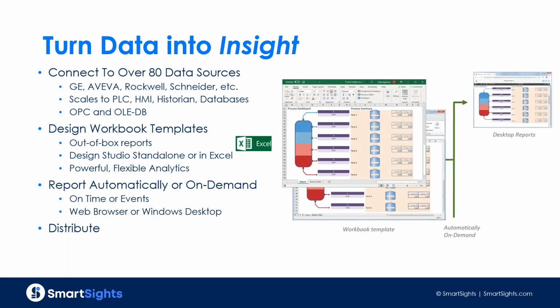Once you design the report and the data it's going to return, you can use that template to generate reports right on time, on event. So think of generating something automatically at the end of the shift, end of the day, end of the week or month, or generating a report based on a process event like a batch starting or stopping, or an alarm occurring.